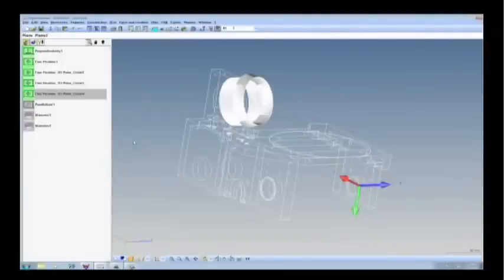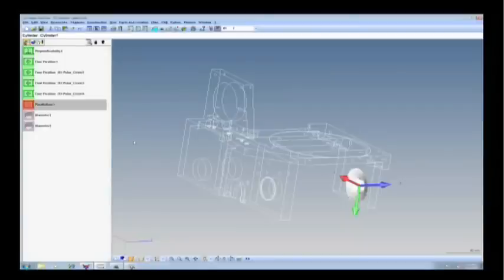Are there any types of parts that are not ideal for CT scanning? Like I explained earlier, in the world of CT, the two most important things are size and density. As long as I have enough power to penetrate through the part, I get a good signal on my detector. If I put something like stainless steel in front of a 225,000 volt system, the X-rays won't have enough energy to penetrate through a part like that, so I wouldn't get a good signal.